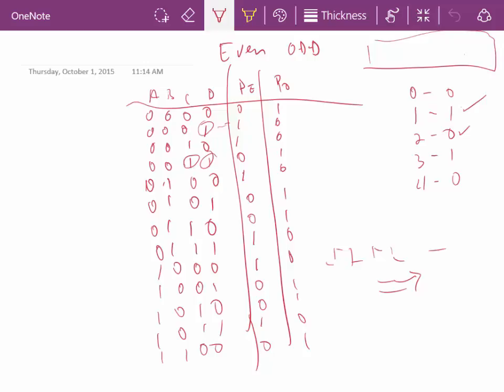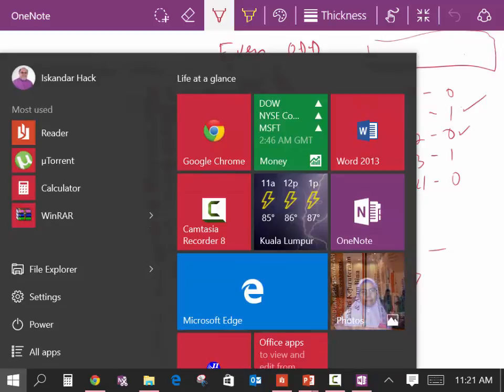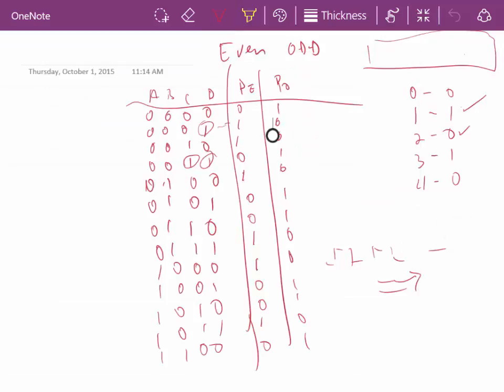It's still the most common way of doing a memory check. When you go through your system, when you first power it up, it goes through and checks all the memory. It's actually using a parity check process. Now, they've actually gotten a little bit more elaborate, where they write a series of 1s and 0s and test them, because the computers are much faster at doing memory checking.